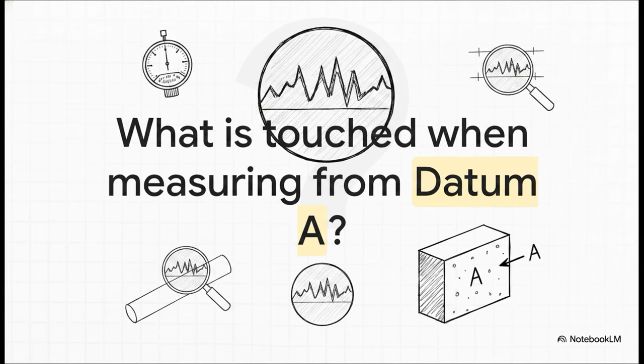So let me ask you this. If that perfect theoretical plane doesn't exist, what is a machinist actually touching when they set up their indicators to measure from, say, datum A? If you zoom in with a microscope, that flat line you see on a blueprint is actually a jagged mountain range of microscopic peaks and valleys. So we've got to solve this core mystery. What exactly are we measuring against out there in the real world?